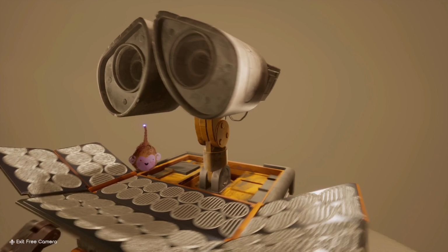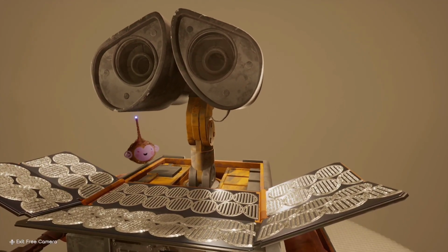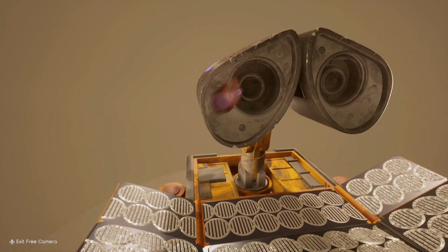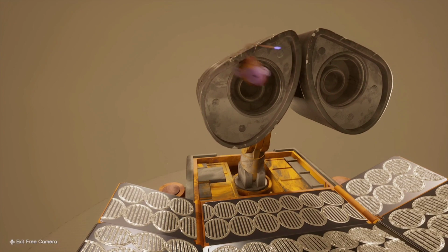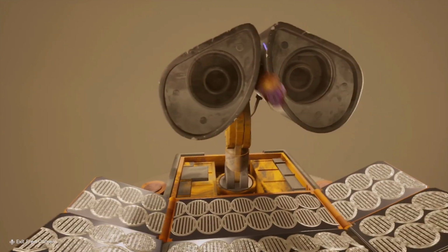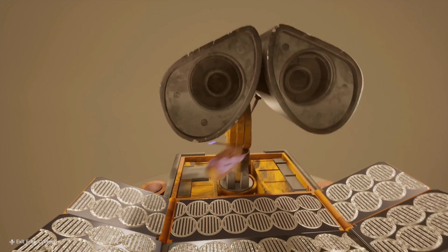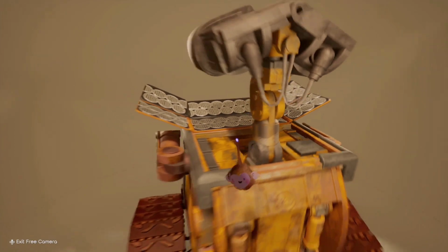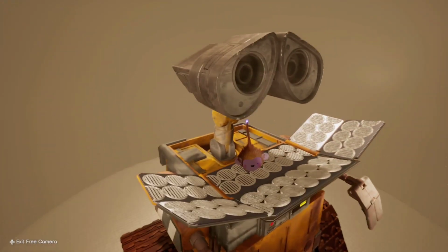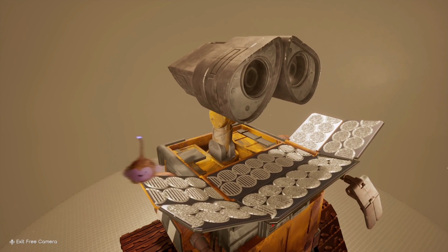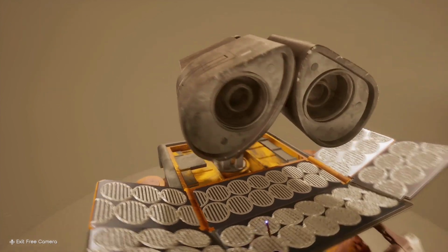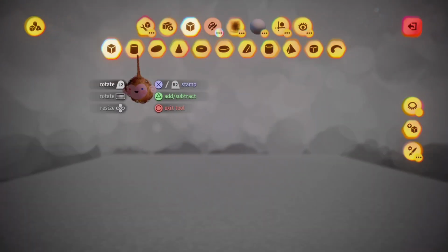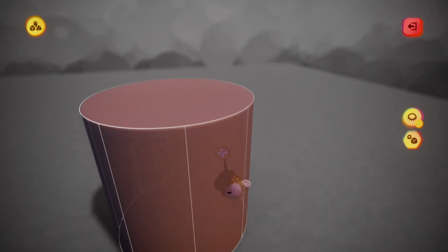And most mechanical shapes, like his eyes even, I'm using a bevel technique to get this shape. So there's a bevel here that's larger than this bevel, which is small. And it's not just cubes that you can bevel and chamfer, it's also round objects and cylinders that you can bevel as well. So with cylinders, how do you do a bevel on this?